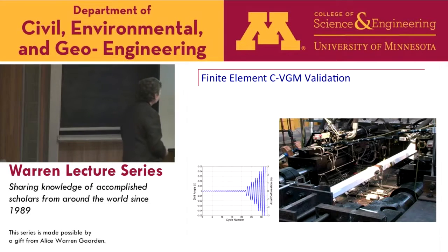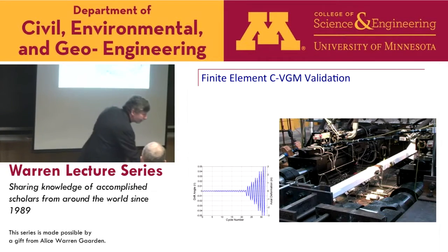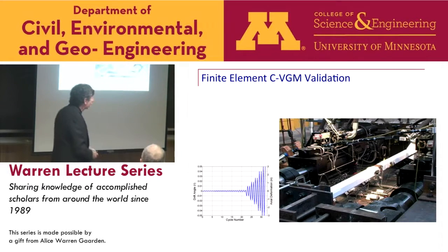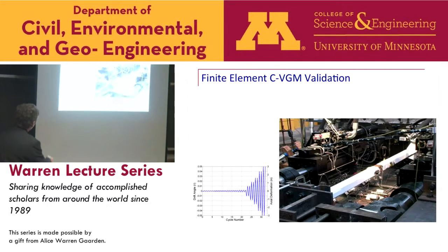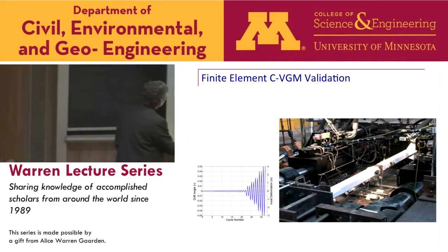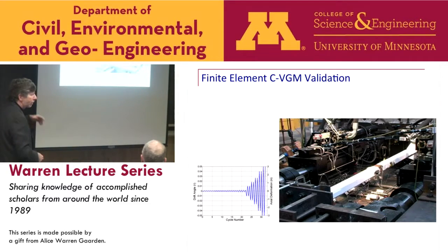So this was an HSS tube. We did, I think, 4 by 4 inch and 6 by 6. These were about 8 feet long. Let me just go back for a minute. Putting it through that cyclic loading you see over here, we see the global buckling, then local buckling, and towards the end of this you might see a fracture develop there. So we did a number of specimens here, highly controlled.